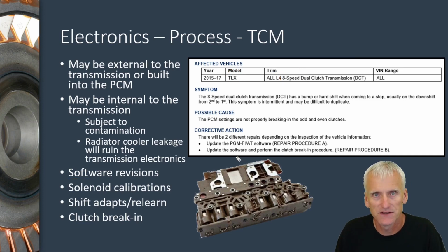As far as module location, sometimes you'll find a TCM located in the valve body, in the transmission fluid inside the unit. Sometimes you'll see them mounted on top of the transmission. And then sometimes they'll be incorporated in the PCM, and the PCM basically means it's going to have engine controls and transmission controls. So it could be different on all different types of vehicles.